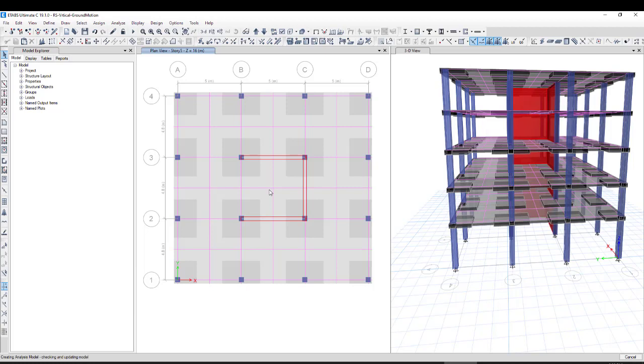Actually, in some areas maybe the vertical earthquake effect is very high. I have seen in some recorded earthquakes that the vertical direction recorded is even similar to the horizontal, X, Y and Z. So be sure, if the region is a high seismicity region, you should consider these parameters or this direction. Now we can check.